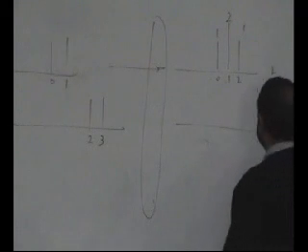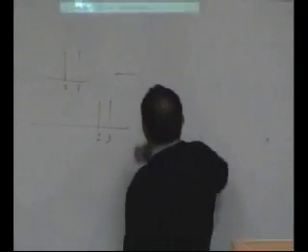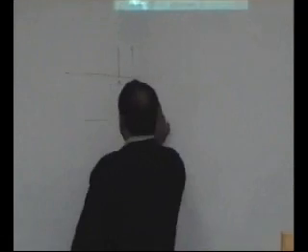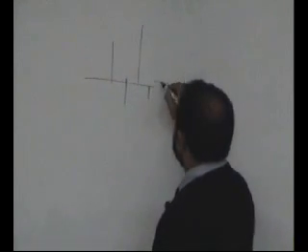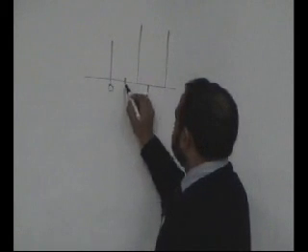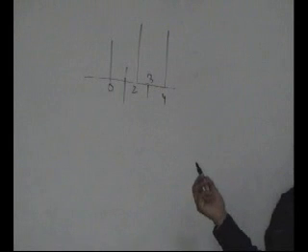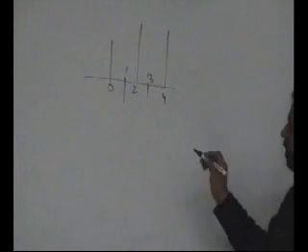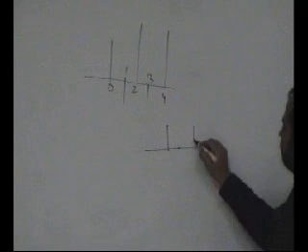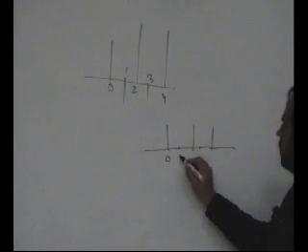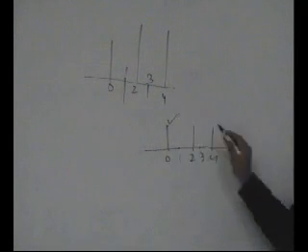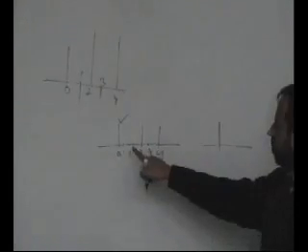An example of a system which is not time invariant, and this is for sure linear but not time invariant, is a decimation system. All you are doing is that you keep one sample and drop the other. Let's say if this is your signal, 0, 1, 2, 3, 4, keep this sample and drop this.